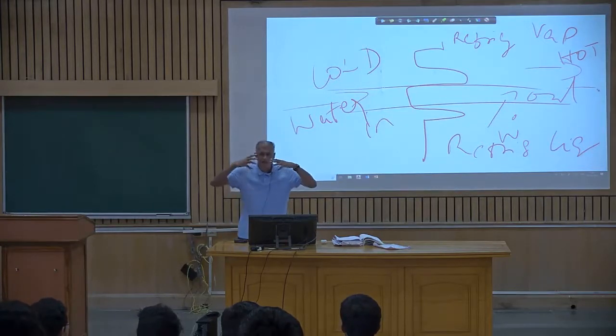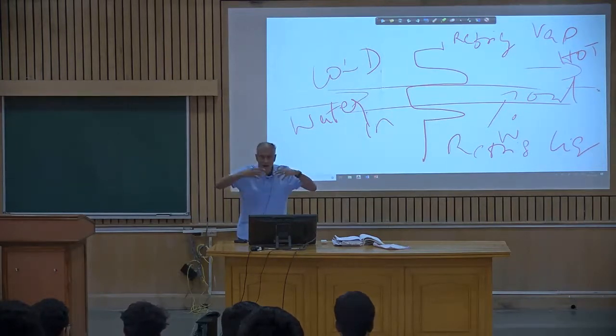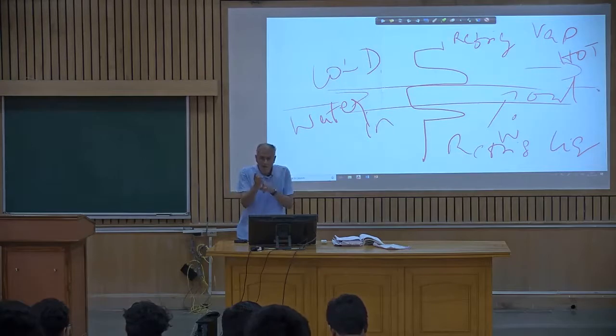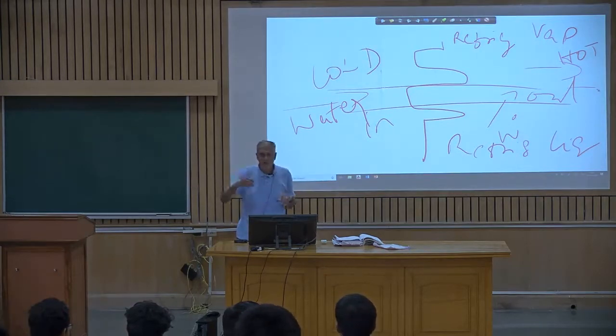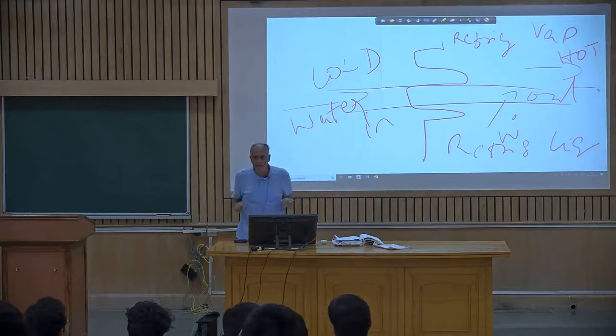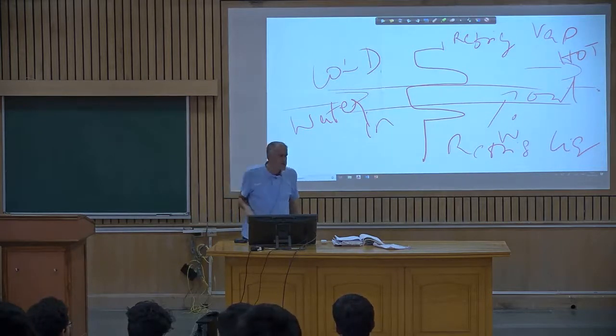So how does this viscous melt actually go uniformly and fill these button cavities or pin cavities or other very intricate plastic parts that you have seen, pens, pen handles? So without squeezing, will it go in and take the shape? You have to squeeze it. So they go through nozzles. So you literally squeeze the melt.